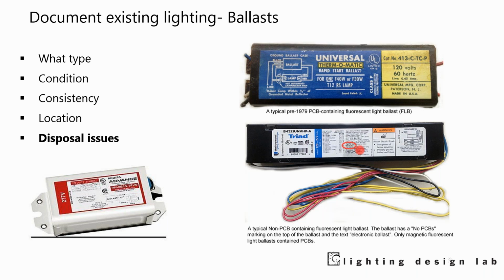Most modern fluorescent fixtures, or even high intensity discharge fixtures, are going to have no PCB in them. And then you want to find out too the voltage, right? Do they have 277 volts on their system, or is it 120 or some other voltage?